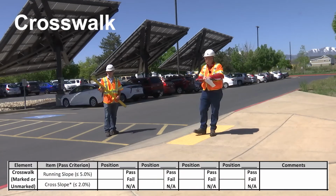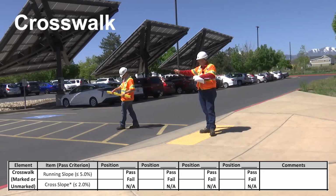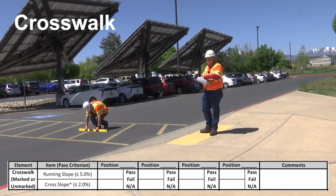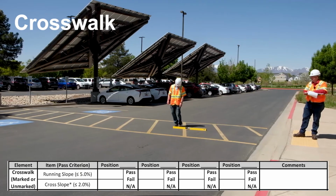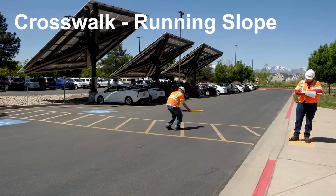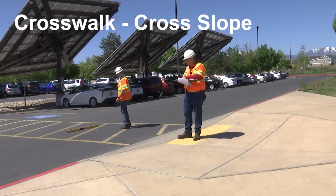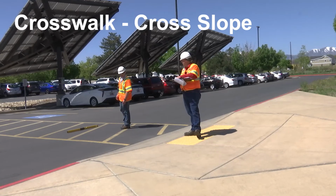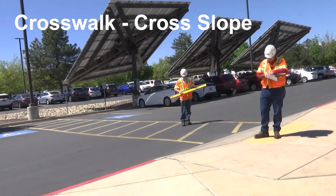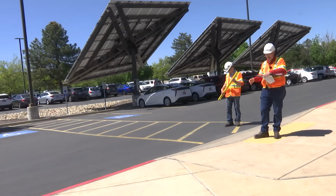Next on our list is our crosswalk. We look at our crosswalk and see if it is a marked or an unmarked crosswalk. Here we have the striping that leads us out into the road. So we have a marked crosswalk, and we'll take the running slope and the cross slope of this crosswalk. Here we have our running slope of 2.9%. We are less than 5%, so we're okay there. And we have our cross slope of 0.3%, and we're under 2%, so we're okay there. Once again, it is a mid-block, so our cross slope can be up to the road grade.